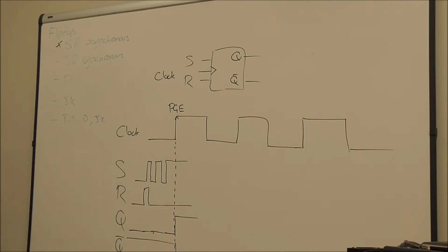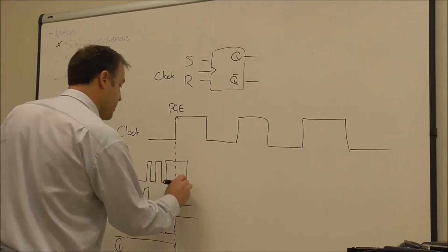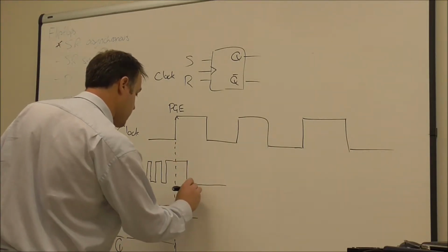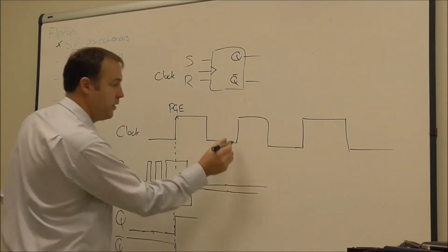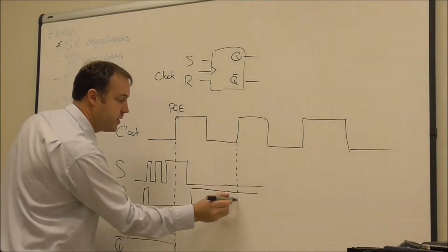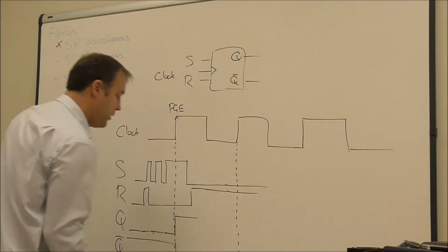Okay. Likewise, if S goes back to 0 and R now goes high, it's not until the next rising clock edge that it would change.